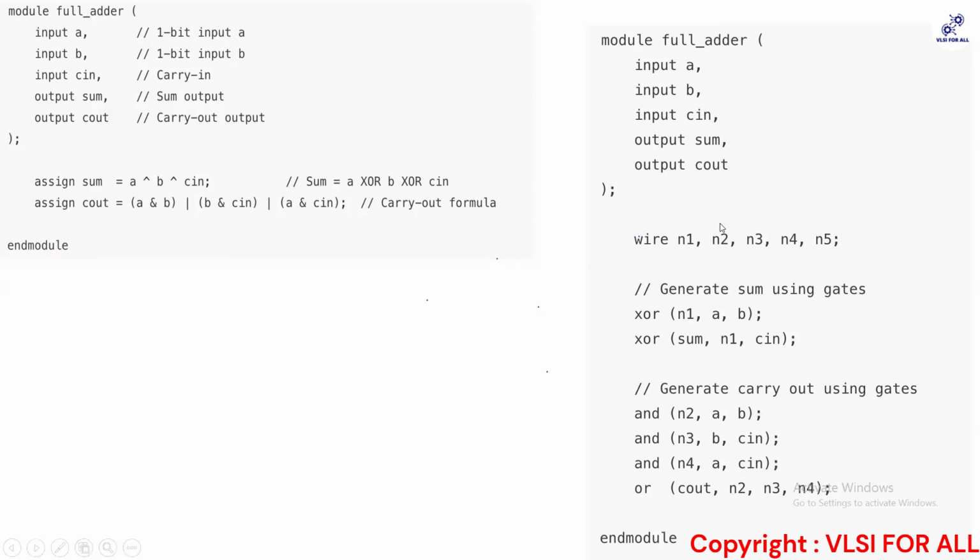Now, if you ever look in your netlist, there will never be an assign statement. If there is an assign statement, definitely it has to be caught at your early stage. There are a lot of sanity checks that the synthesis person does, where he validates the netlist and everything. So the netlist should not have any assign statement in it.